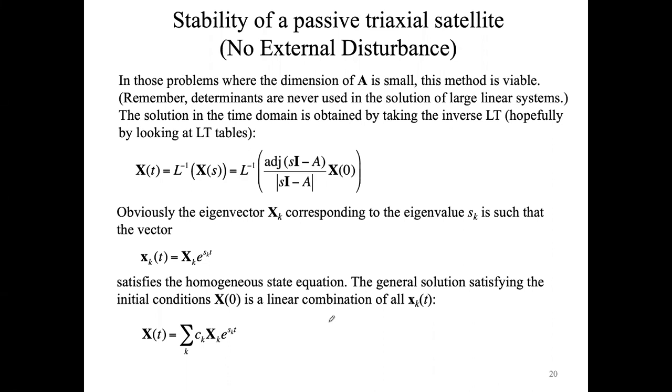So how to deal with the solution of a differential equation, and if you want to see, for example, the modes of the solution. So here we are doing exactly the same. So we are trying to determine the modes of the system by using a classical approach in time, or by using the Laplace transform. What you have demonstrated is that indeed we are going to have exactly the same form.